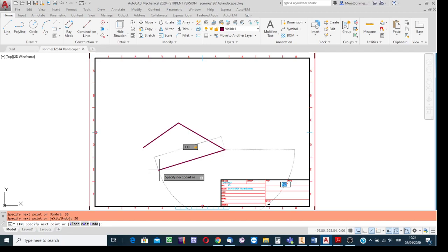Now I see that the angle is ready to be considered by the system as measured in the clockwise direction relative to the horizontal dotted line. Well, according to a right angle, it is now an obtuse angle. Say that it is 160 degrees. Okay, press enter.